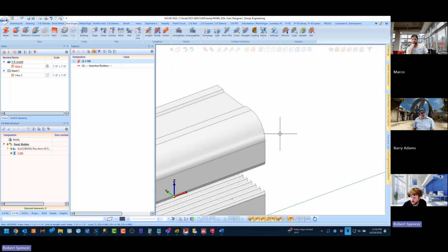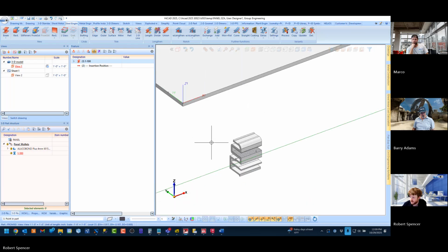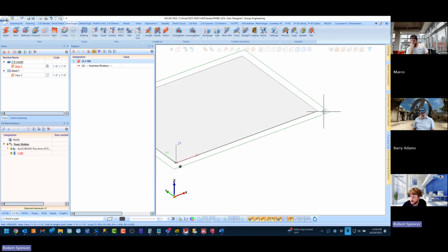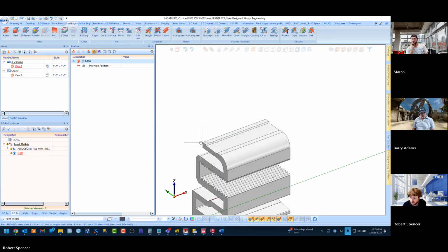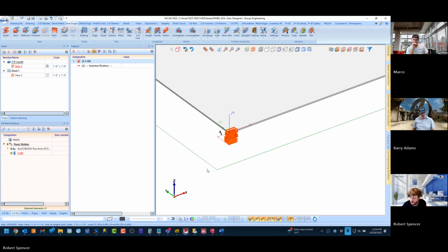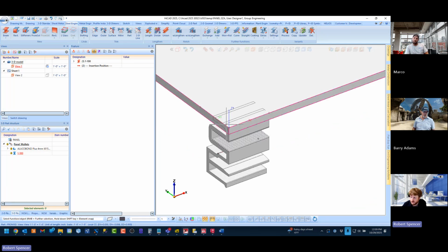Next, I need an X direction. So I'm going to use the one down here. One reason why I kept this so small is so that I'm not having to zoom down here to the other end to select these points. Third one, align this to here, and watch what happens. It jumps to the position. So it is now living in this model per the relationship set up with these 3 special points.